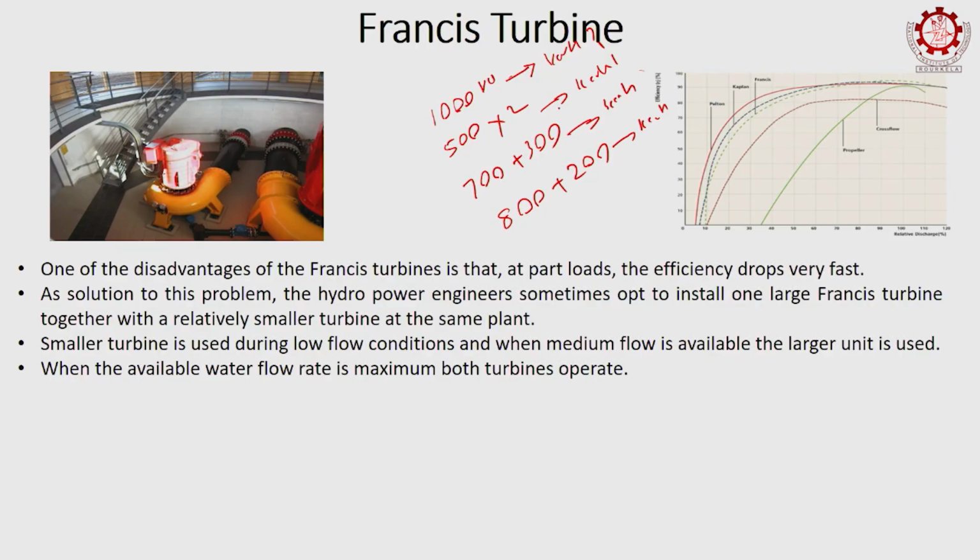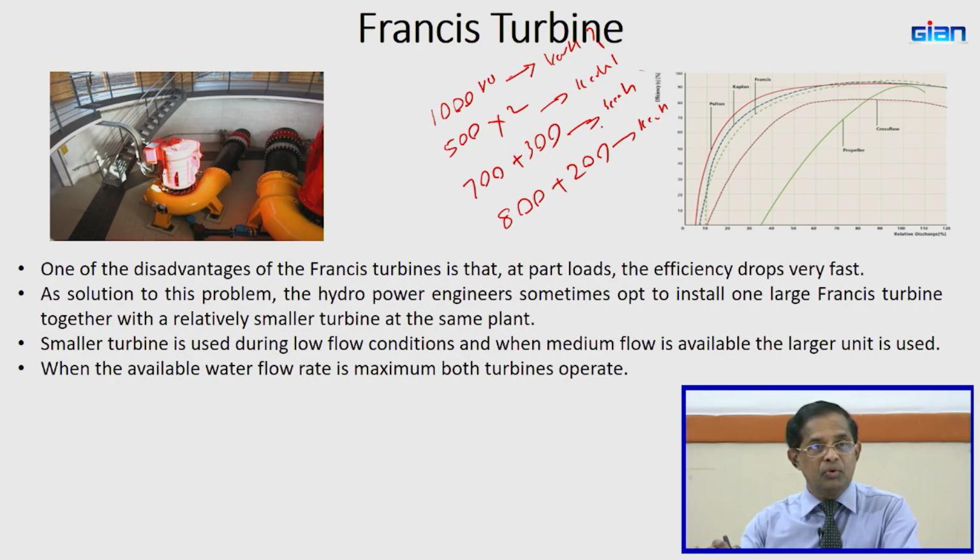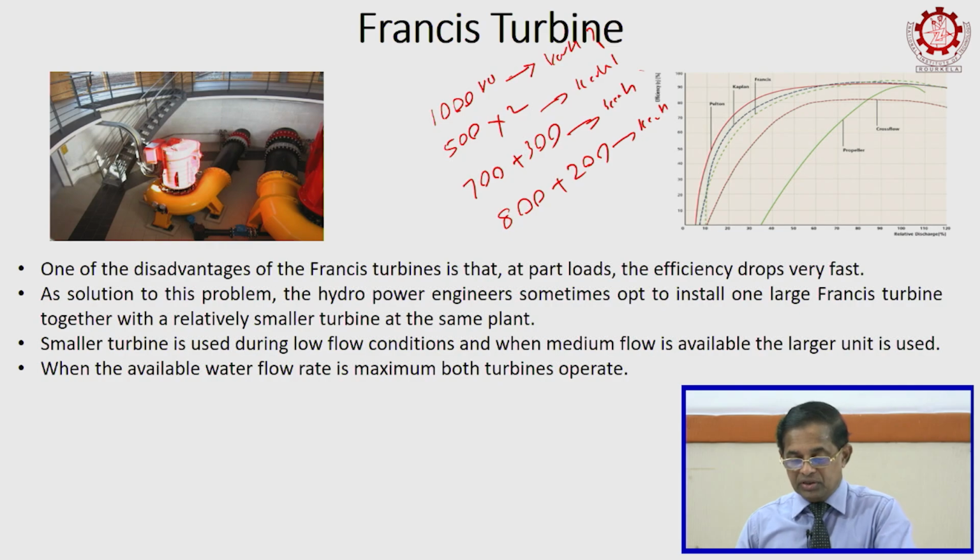Then you must see whether the increase in power generation is worth the additional cost over the long term, right. That financial analysis you also have to do, because otherwise, just for a few kilowatt hours, if you duplicate everything, control systems, synchronizing and all the control panels, then it might not be worth it. So, only after doing the calculations should you decide which configuration and which capacities to use.